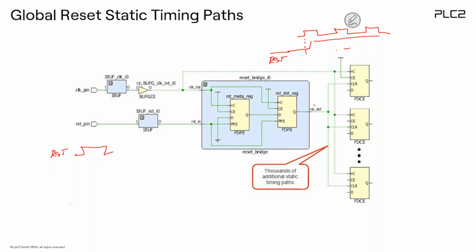The problem is because now it's synchronous, Vivado will actually try to optimize this, because the requirement for this net is that it's activated at this edge, but must be at all destinations at this edge. This means the total time is T, the period of the clock. So there's a requirement for all of the signals here.